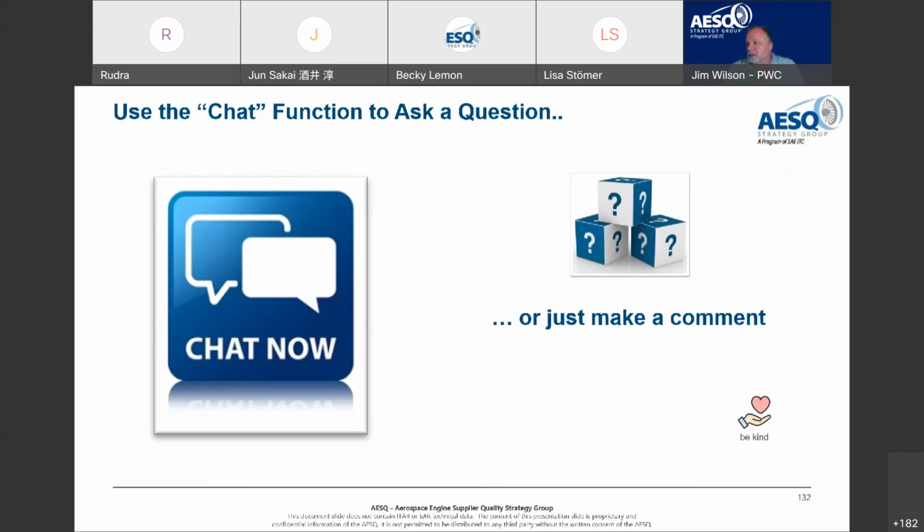From Connie: what is the meaning of accurate visual inspection? She says her company is compliant to the 700 lux, which is the AS13100 standard, but not 1000, which is what the standard calls out for accurate visual inspection. 700 for regular and 1,000 for accurate visual inspection. What is the meaning of accurate visual inspection? We are compliant to the 700 lux, but not 1000.